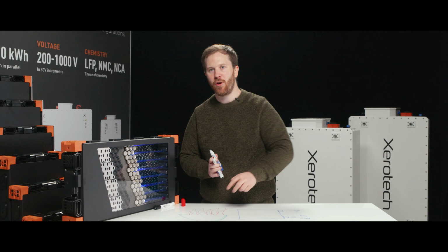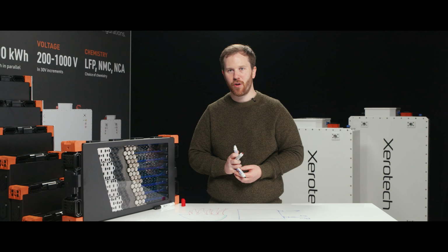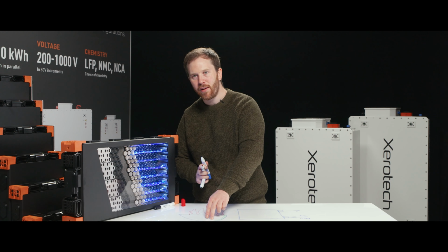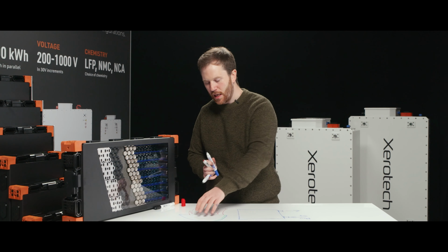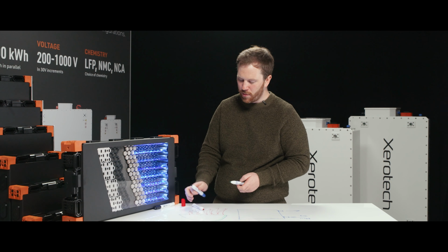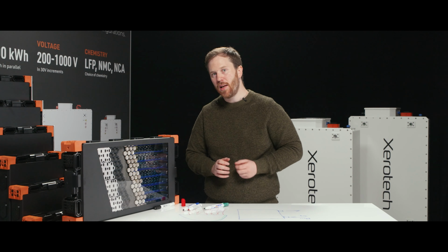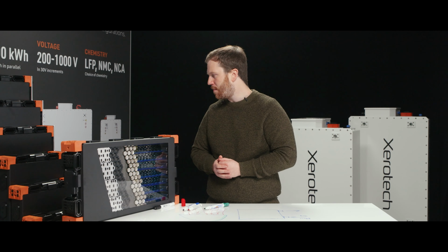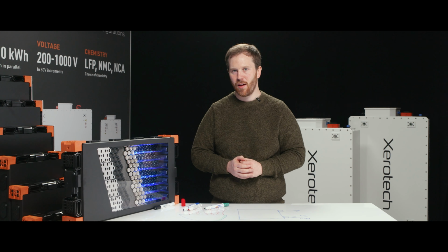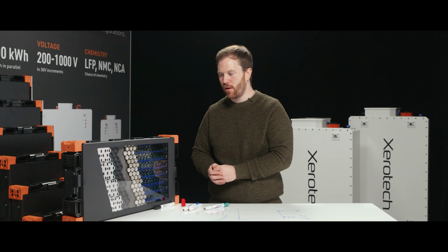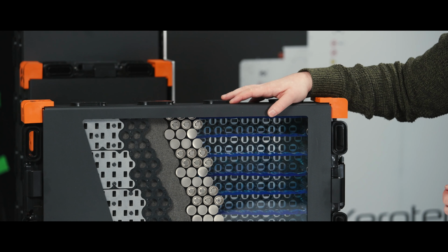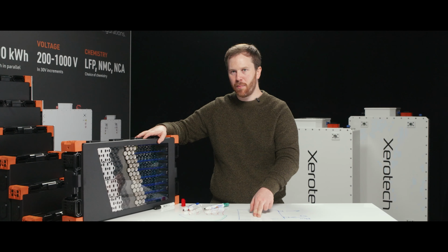You need massive cooling pumps to do this. Thousands of horsepower of cooling to drive that rocket fuel through those nozzles. But it results in extremely high heat transfer to deal with this. But the temperature gradients are also going to be very high. And the challenge with battery pack designs, and it's a problem even today, even some of the best engineers, the best pack manufacturers in the world have differing approaches to this, and some are maybe good and some are not so good, is that you actually don't want to maximize heat transfer coefficients in a battery module because it results in massive temperature gradients.